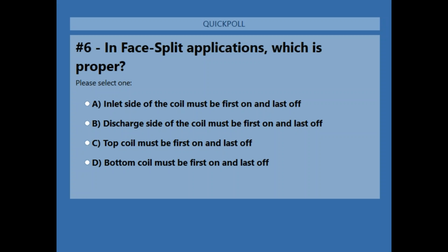Yep. Chun asks, is one control solenoid enough for multiple evaporators? It depends. So we look at face area of the evaporator coils. We look at line length. We look at a lot of different things to decide if we need a solenoid valve period in a single circuit. And I'm of the opinion we always need a liquid line solenoid valve. How many you need, it depends on what you're doing.